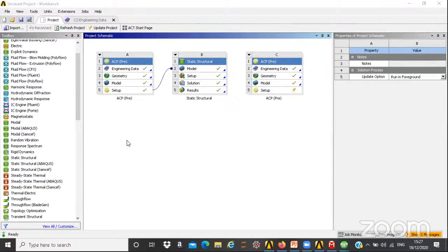Now, we have not designed the control system as yet that could manipulate input variables or material properties, because practically, when we put it into industry, what the control system is going to do is continuously measure the output. In this case, let's say the output is surface roughness. As soon as it measures some output, wherever it is, 0.5 micron or 10 micron or 5 micron, it will try to manipulate the input variables automatically, the cutting parameters or machining parameters, in such a way that 1 micron is achieved, and it remains stable at that.